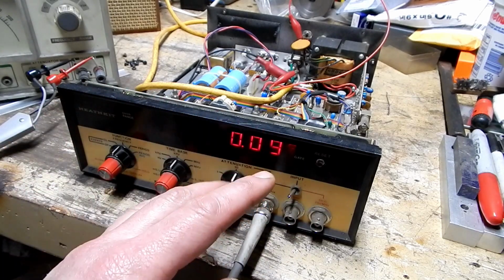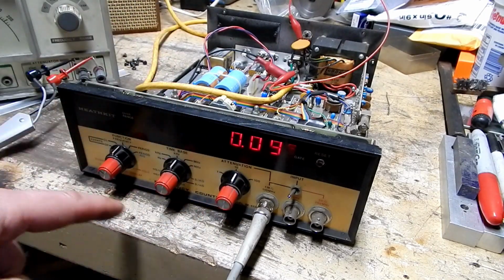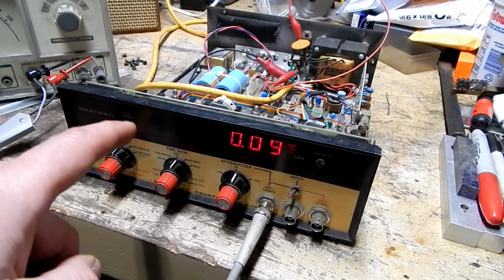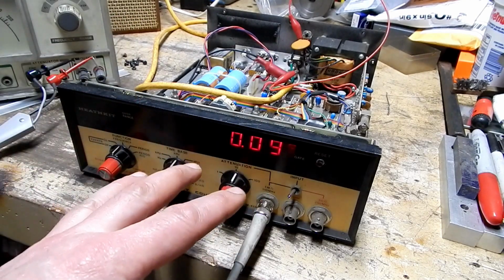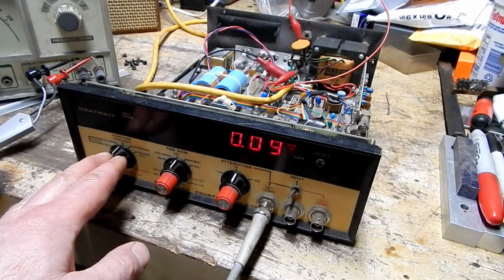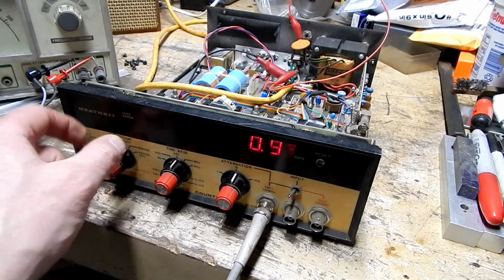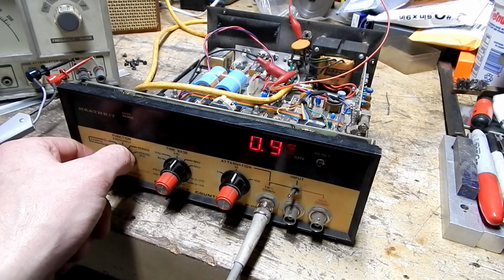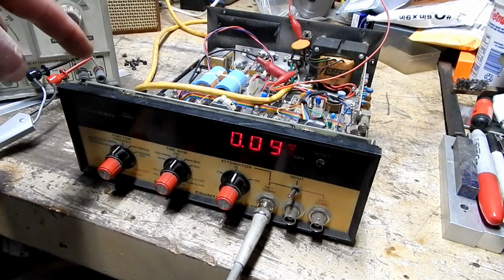All it does is sit there and count how many times it sees a pulse. And the sine wave frequency going in there is acting like a pulse. Well, at least that's what the counter sees it as. But for the actual measuring of the frequency, or to show the period of the frequency, it needs to make a comparison to a reference frequency.